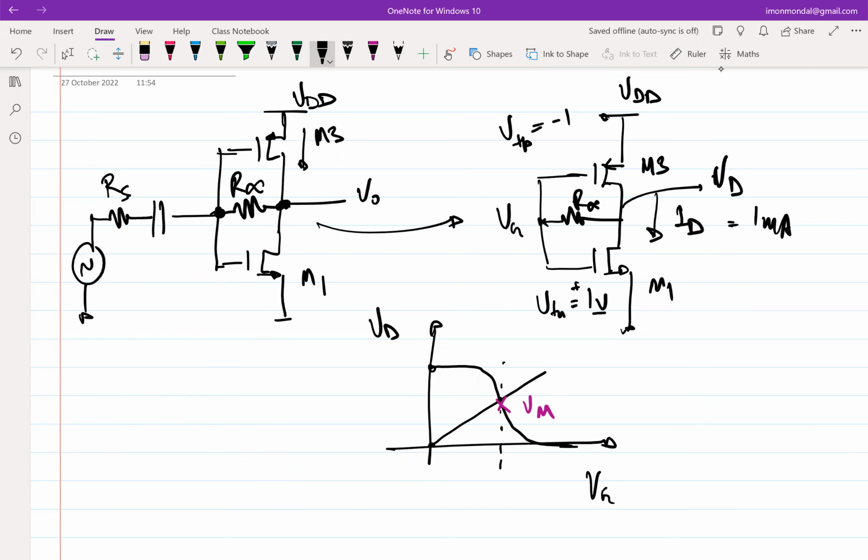Let's assume it's a voltage. You have a common source amplifier biased with a constant voltage. Then the threshold voltage decreased in an NMOS common source amplifier. What will happen to the current? It will increase, right? So in this case, let's assume that the relative strength of M1 and M3 are the same. Starting off, we assume the relative strength of M1 and M3 are the same, which means mu Cox W by L is the same and the threshold voltage is the same. Now nothing else has changed, but the threshold voltage has decreased in both cases by the same amount, which means the relative strength of M1 and M3 is still the same.